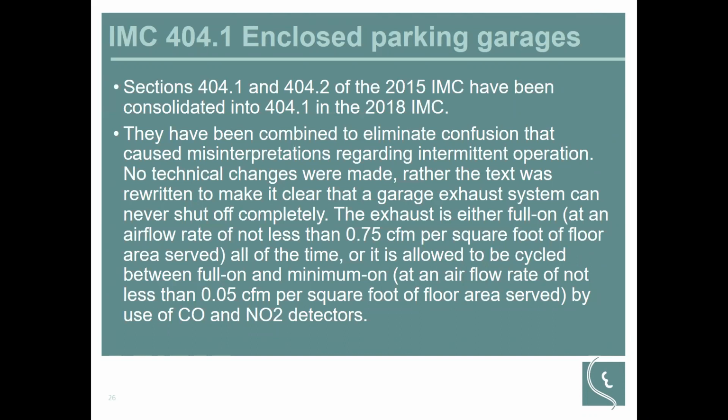Now this will come into play a little bit later when we talk about energy recovery, because this is now a continuous exhaust. If you are in a conditioned parking garage, energy recovery may begin to be required here too. But with this fairly low minimum airflow rate, a 200 CFM fan could serve up to 4,000 square feet of floor area.